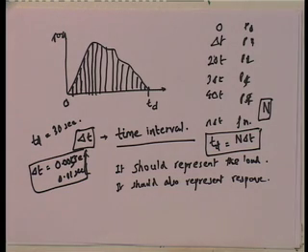Of course, if you have blast loads, which typically last milliseconds, 0.005, which is 5 milliseconds, does not make sense for delta t, because if your blast load lasts for 5 milliseconds, obviously your delta t has to be significantly lower than that. But for other kinds of loads other than blast loads, delta t equal to 0.005 or 0.01 is good enough for representing the load.